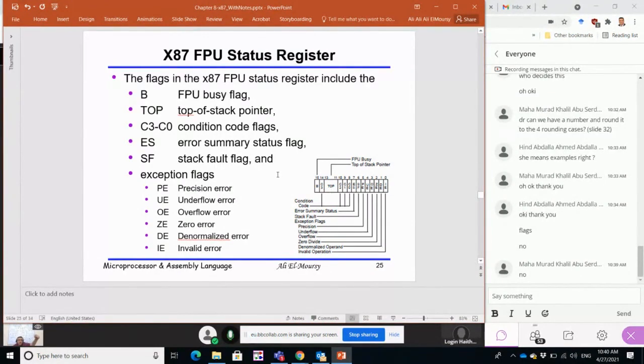Okay, remember that the X86 fetches some instruction, recognizes that this is a floating point instruction, sends it to the floating point unit, and returns back to the main program. Will it proceed? It cannot proceed. It has to wait for the floating point unit to indicate that it is done, that it has finished its execution. The execution of floating point instructions takes multiple cycles.